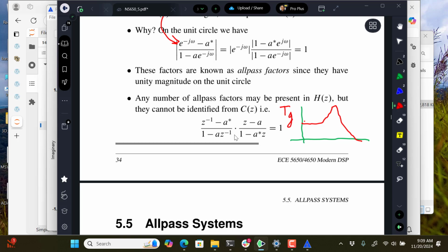If that was a group delay and it peaked up right there, what we could do is put an all-pass filter in somewhere, so that hopefully we're going to get a flatter group delay response. The all-pass filter would try to put some group delay in at lower frequencies and some group delay in at higher frequencies, so that in the band of frequencies of interest for the bandpass filter, at least we flattened the group delay. Not made it go away entirely, but for the band of interest, we've made it flatter.